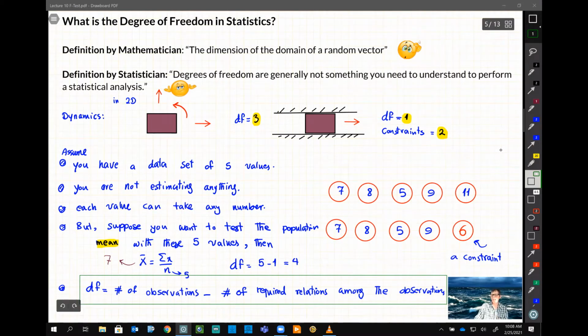So for an ideal gas, you would have to specify 2 properties, or for any single phase substance, you specify 2 properties. But if you have two phases present, like vapor and liquid, that effectively is another constraint. And now the degree of freedom would go down to 1. In other words, you would pick the temperature and then you look up the saturation pressure from the steam tables. So generally you can think of the degrees of freedom as the number of pieces of information you need to totally specify the state of the system.